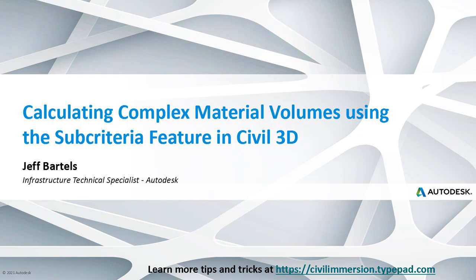Civil 3D makes it easy to calculate average end area earthwork volumes between two surfaces. In fact, there's no limit to the number of surfaces allowed to participate in a volume calculation. In this session, we'll learn how to define subcriteria. Subcriteria allow volume calculations to be extracted from areas defined by multiple surfaces.